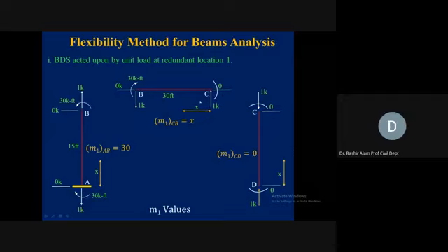The moment cannot be applied here, because it would have to be resisted here and transferred to the free end, which does not have the capability to resist. So the only point where it can be resisted is joint B. And how much? The couple moment is 1 times 30, and it was causing a couple in the counterclockwise direction. So it has to be resisted by a moment of 30 kip in the clockwise direction. So here we show the 30 kip moment.